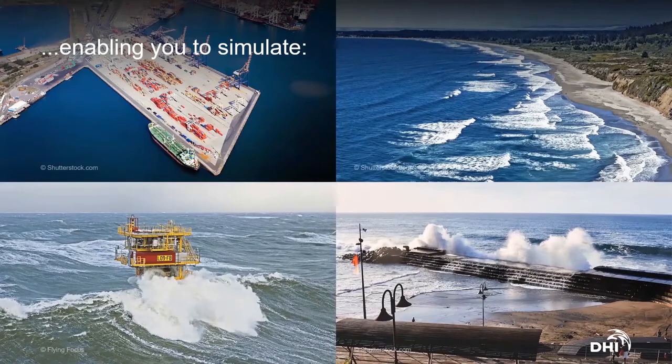It is solving the three-dimensional Navier-Stokes equations, and it is capable of solving any wave fields, such as short wind seas and long swell seas. We can even handle tsunami waves, and of course all of the nonlinear transformations happening in the swash zones as well.